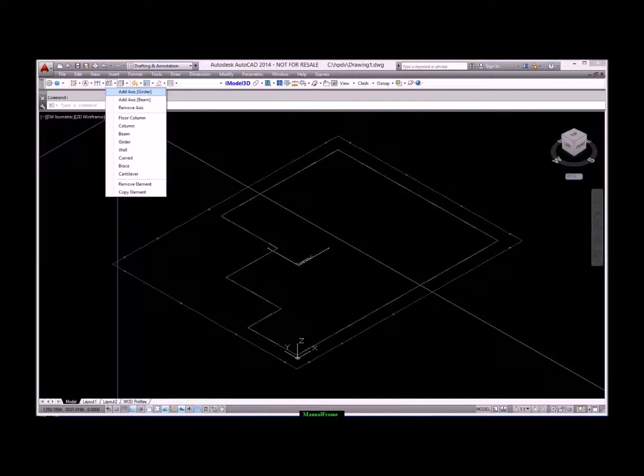The main icon loads this dialog box which allows you to specify the basic information about the space frame such as name, number of floors, floor height and slab thickness. You can also specify the slope of each floor as in modeling garage structures. This dialog box is used for both automatic and manual options.